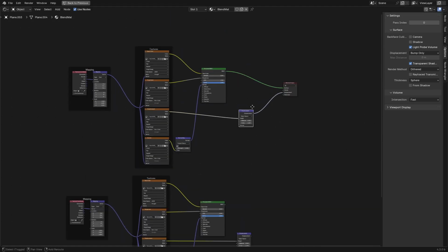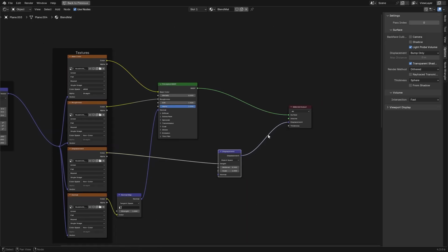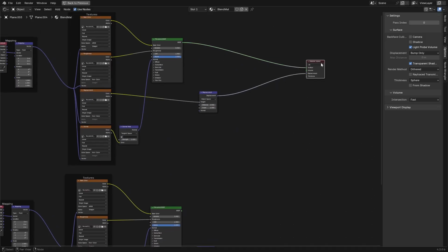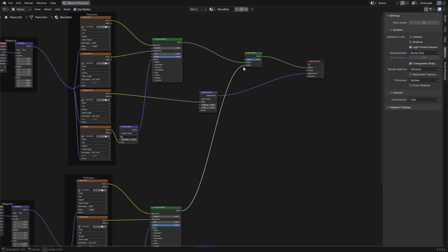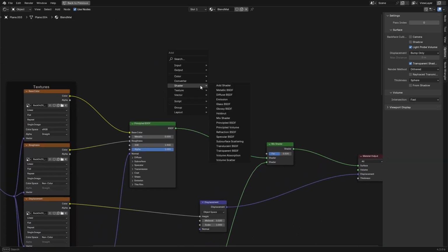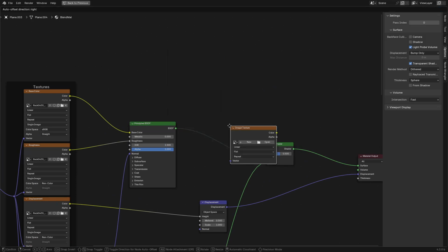And we'll get this all going. It might be a little bit squirrely as I go through this, but we'll try our best. All right. So here we go. Let's do a Shift-A, create shader, mix shader. Drop it on there. We'll drop this one on here. We're going to go ahead and create a texture, image texture.